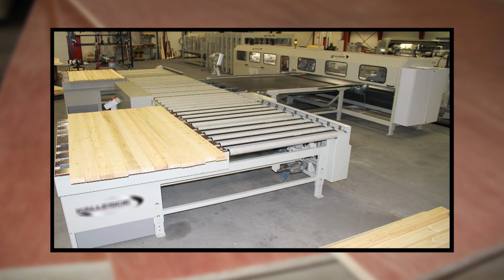The short sections of a core veneer are then laid crossways on top of the glued back, and the whole sheet is run through the glue spreader a second time. Finally, the face veneer is laid on top of the glued core and the sheet is stacked with other sheets waiting to go into the press.